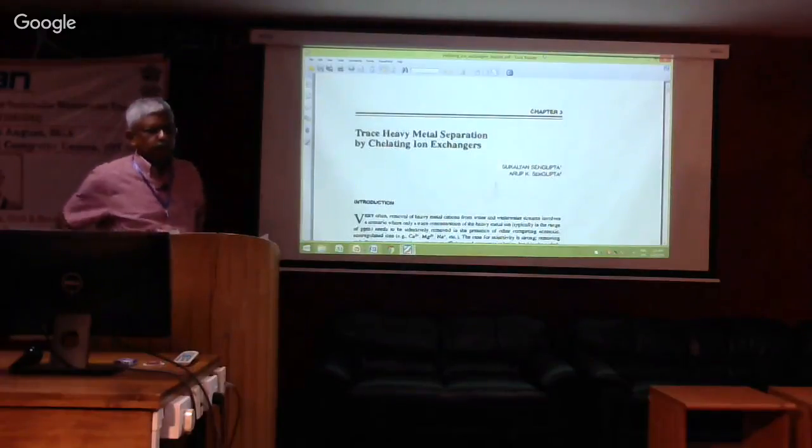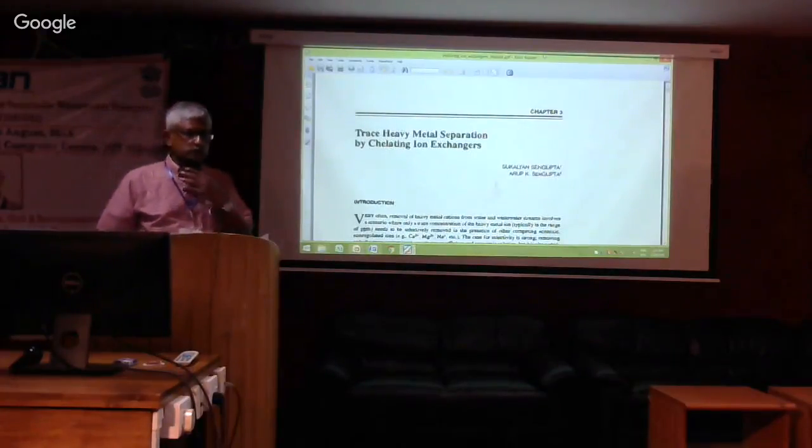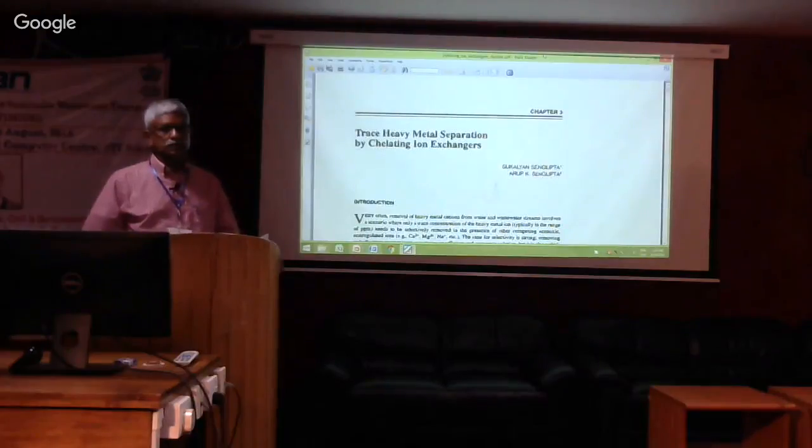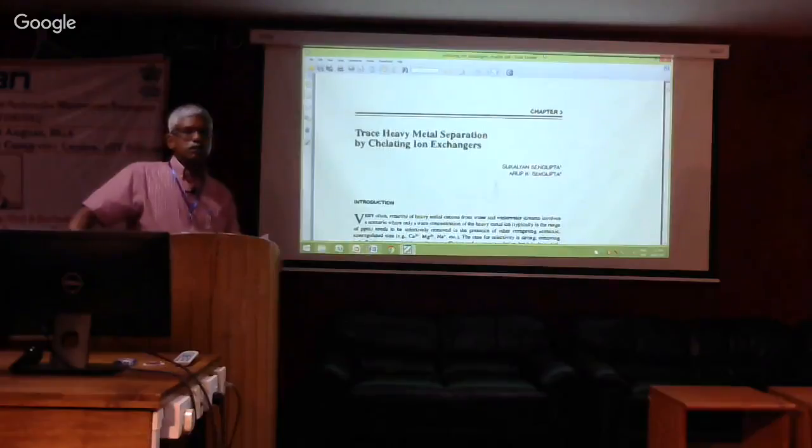Since we are treating human waste, if we can treat the liquid part in parallel with this zeolite in our system, that will be actually great. That's why I wanted to know what is the efficiency of this zeolite and how much it can really work upon. If we do it on a field basis, then we have some discharge limits and those things. So how much does it recover?